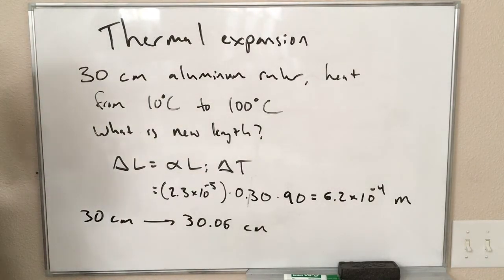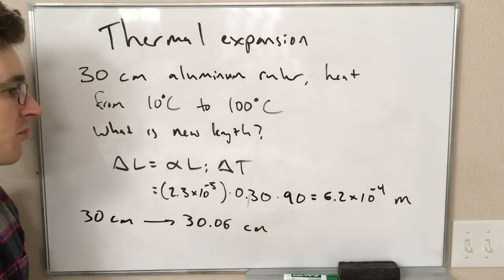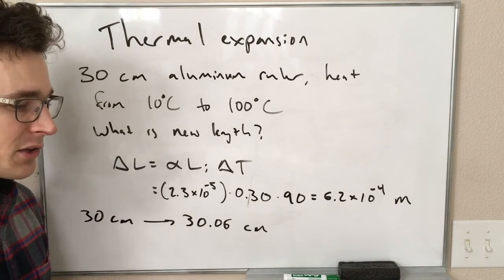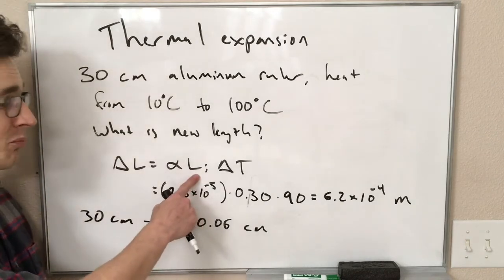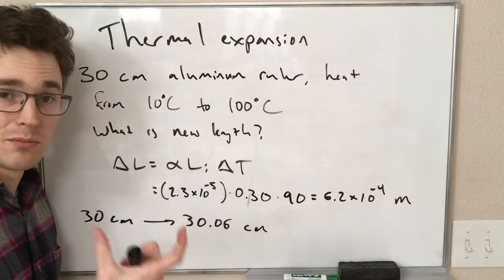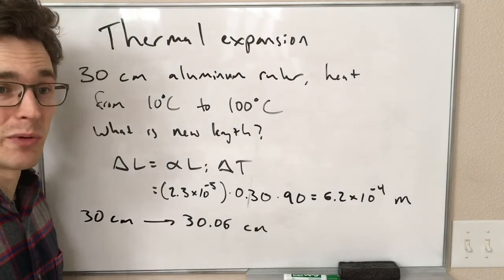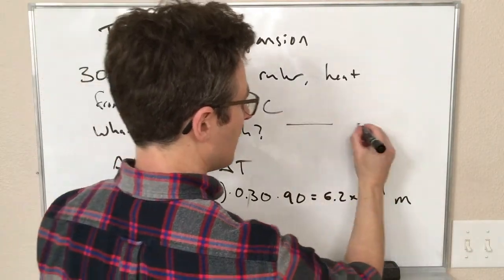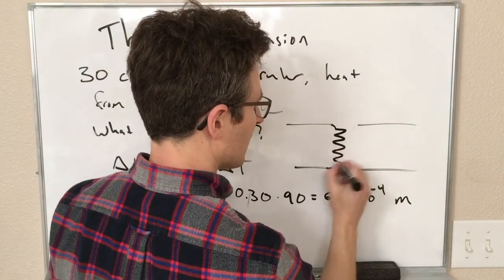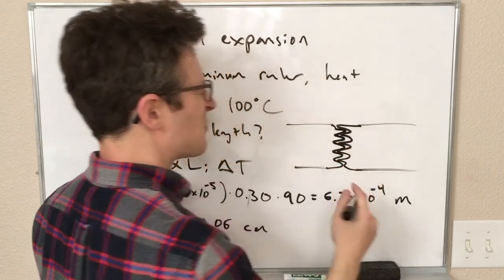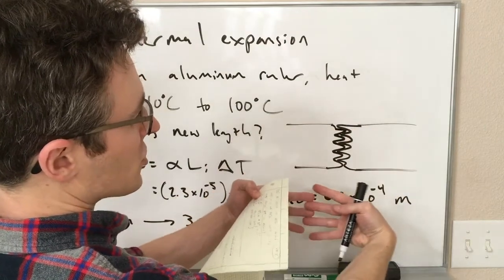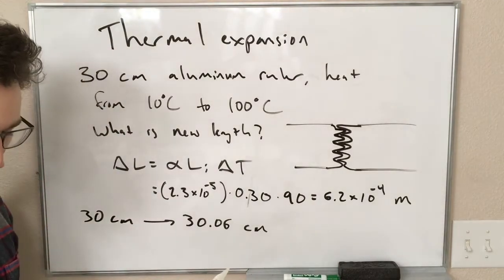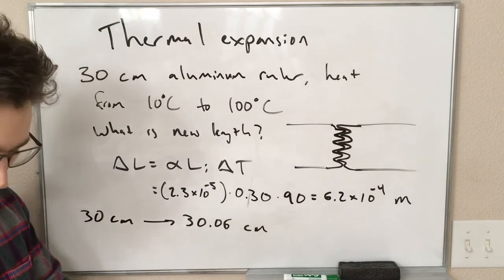There are other far more important examples where thermal expansion matters. The biggest ones I should mention are in things like bridges and buildings. If you have long pieces of metal or concrete that undergo temperature changes, they are going to change their size. And if L is really big, delta L can still be significant, many, many inches. And there are engineering ways of overcoming that. One is expansion joints. If you drive over bridges or freeway overpasses, sometimes you see between two pieces of concrete something that looks like teeth overlapping. This is an expansion joint meant to allow these pieces of concrete to expand and contract, change their length, and still have a solid roadway to drive over. There are some other fun examples of thermal expansion that I'll post some links to on Canvas as well.